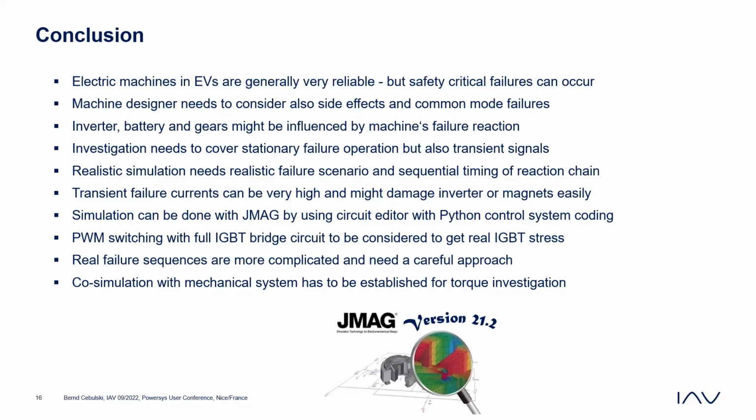And at the end, we also might need a co-simulation with the mechanical system, which I didn't address here. Because there's thermal inertia, and there's changing of the speed from braking, which is also affecting the failure sequence. If the speed changes quite fast and the resolver is stuck, so it doesn't measure any speed anymore, you are running at the wrong frequency. I don't know what's happening in the machine then. Interesting simulation. And there's much more than that. This is just the beginning.